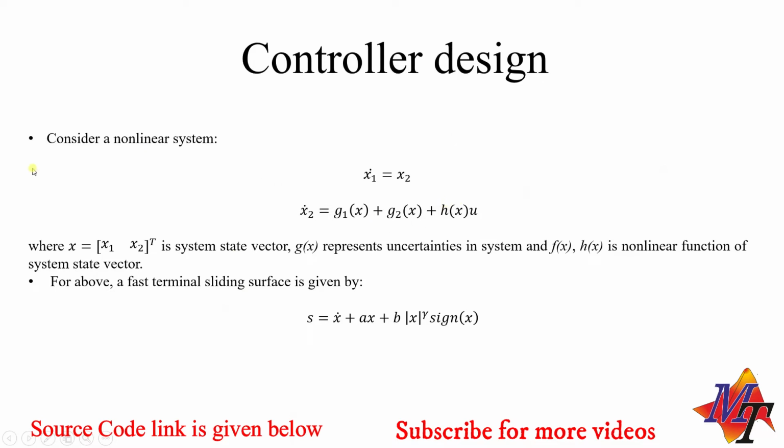Now in general terms, we consider a nonlinear system. Suppose x1 dot is equal to x2, where these are the system states, and x2 dot is g1(x) plus g2(x) plus h(x) into u, where u is the control input. For designing any sliding mode controller, we have two steps. First is to design a suitable sliding surface, and second is to calculate the control input that is applied directly to the system. So x is the system state vector, g(x) represents the uncertainties in the system, and h(x) is a nonlinear function of the state vector.